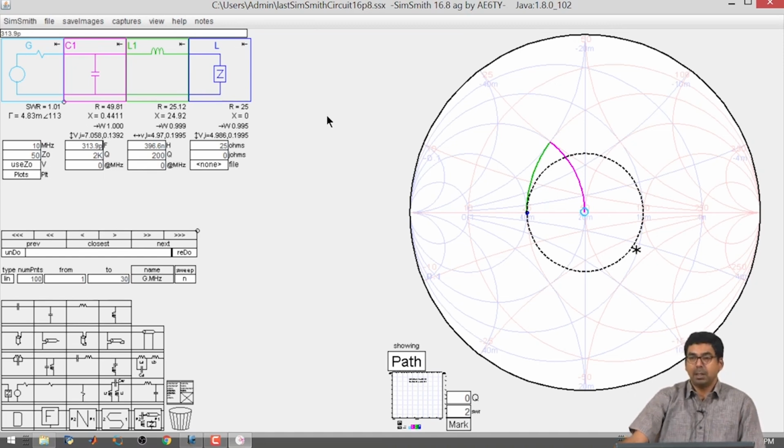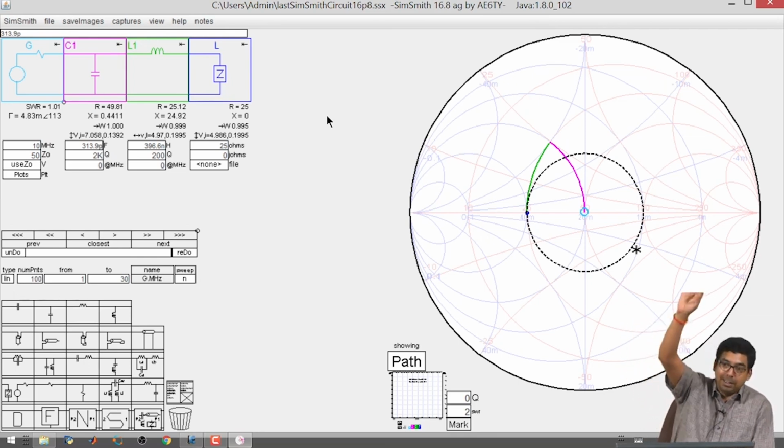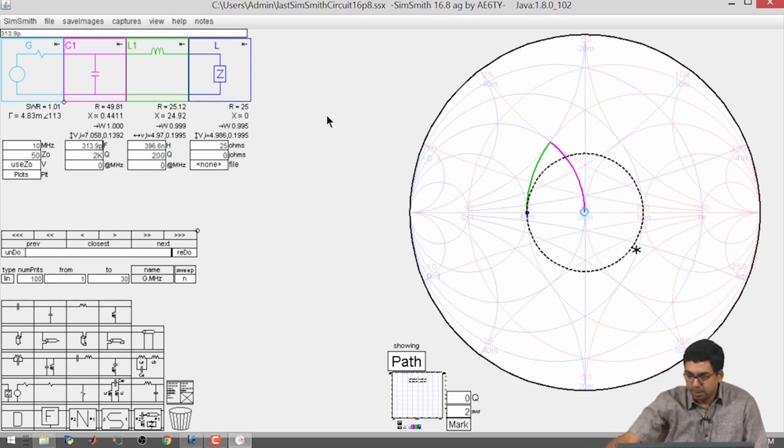Okay. Now, we notice that the resistance will move you along the path of circle of constant reactance if your load is purely resistive, all right. Then adding any series or shunt resistance will move only in the horizontal axis of your Smith chart. If your load is complex and if it is somewhere else, and if you add resistance, it will go along the circle of constant reactance. Okay. But adding a resistor is actually going to come with some penalty, because you are going to lose some power, but adding an L and C will not give you that penalty, and it will allow you to dissipate all the power at the load. This is the most elementary way of doing impedance matching in a circuit.